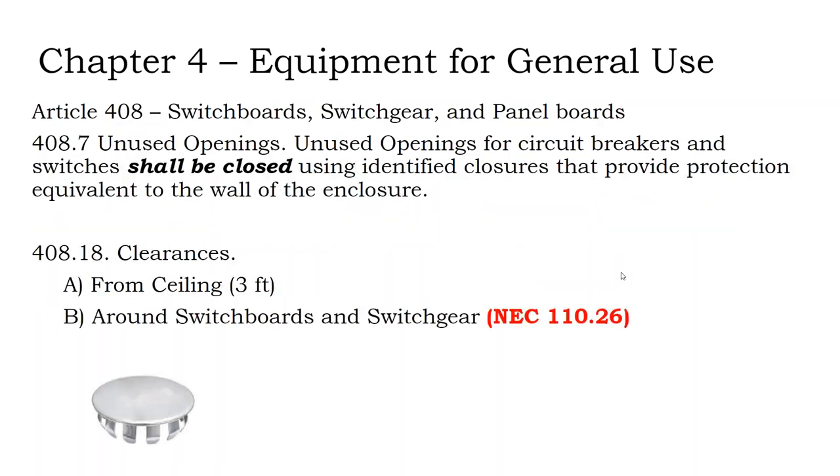So unused openings shall be closed. What that means is if you drill into a box for your conduit run and then end up not using that hole, there are plugs you can buy to fill that hole. You don't just leave a hole in your electrical box, because you'll get wasps and critters nesting inside, which is a nuisance by itself, but could cause issues too. Panel boards, switchboards, and switchgear should be 3 feet from the ceiling.